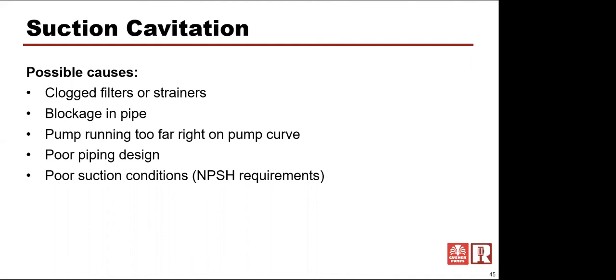Remember, one of the things I talked about in piping design was not having an elbow close to the pump itself. We wanted 5 times the diameter of that suction pipe coming into that pump to get nice, straight, laminar flow. If you had an elbow very close to a pump, it's very possible that you could cause cavitation on some of the vanes on the one side of that elbow as that rotates, and then it would disappear as the pump rotates around, and then reappear, all the way around that pump impeller as it's spinning, depending on what side of the intake pipe it's on.